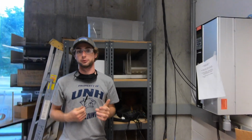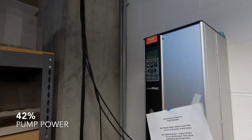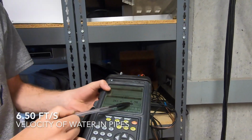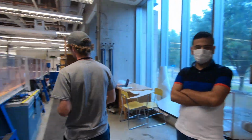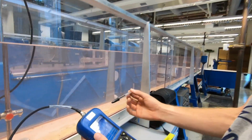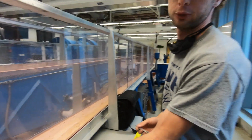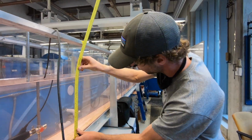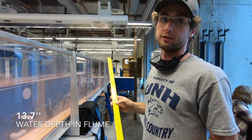So we're now on trial 4 of part 1 of the lab. The pump is running at 42% capacity. The velocity in the pipes is 6.50 feet per second. The Marsh-McBurney flow meter is reading approximately 0.41, or it just dropped, so call it 0.40 feet per second, with a depth of, we'll call that 13.7 inches.